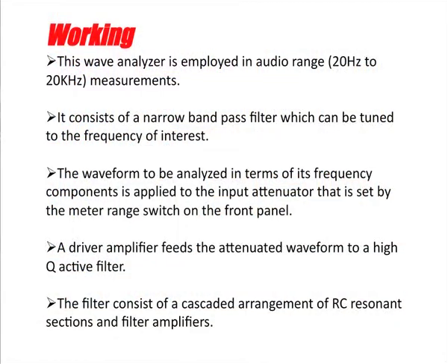This wave analyzer is basically employed in the audio range of 20 hertz to 20 kilohertz. The filter, as said earlier, is the most important component of this type of analyzer. It consists of a cascaded arrangement of RC resonant sections and filter amplifiers.